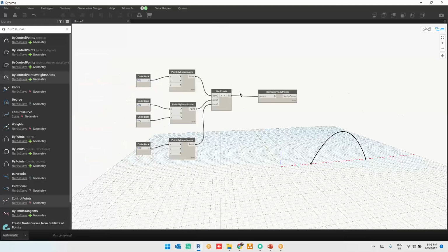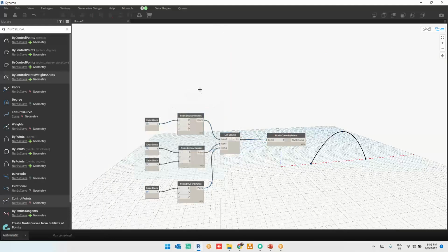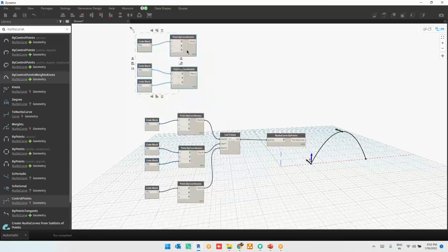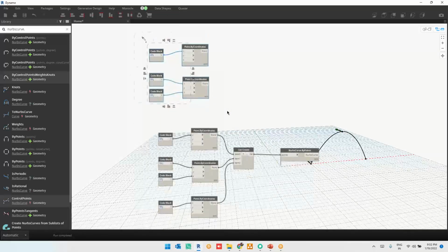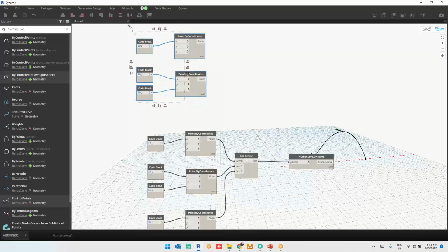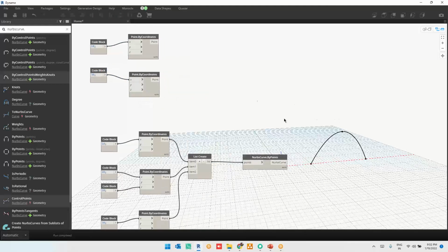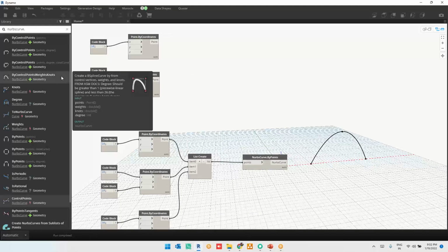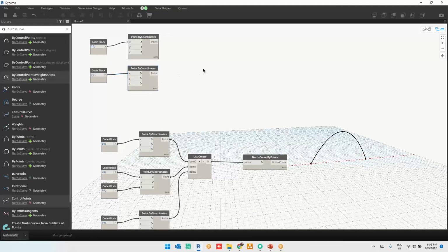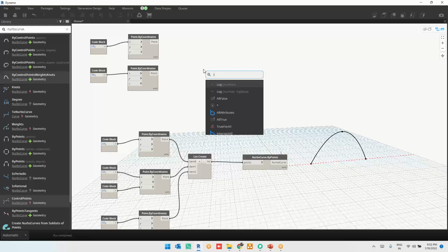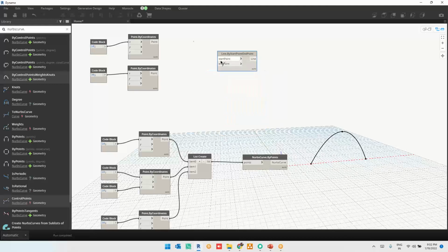So successfully, let me create these 2 points. Let me Control C, Control V. I just want to go with the X value 30, and I don't want this, so let's leave it at 30. Now, if I want to create a single line, Line.ByStartPointEndPoint. Okay, that's it.